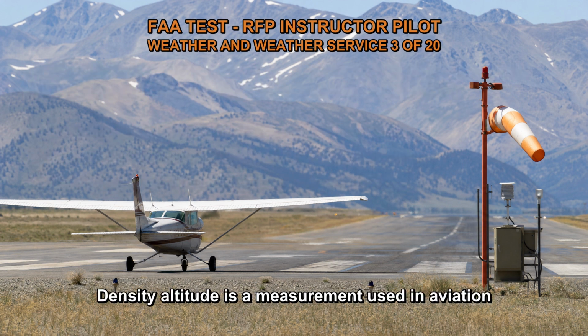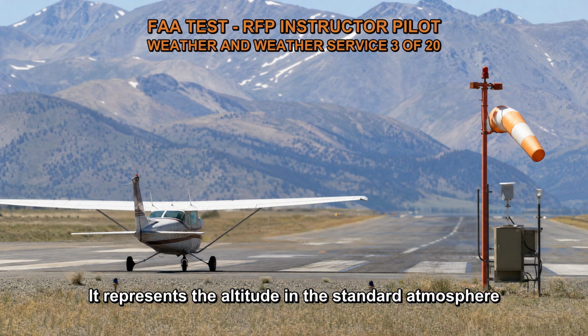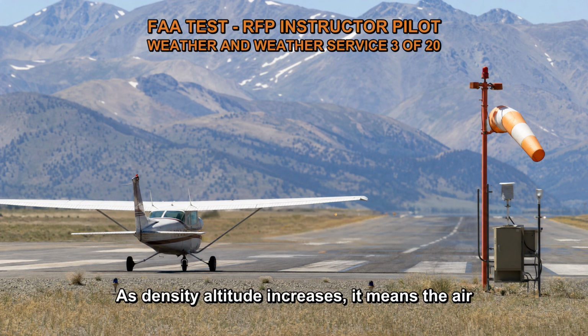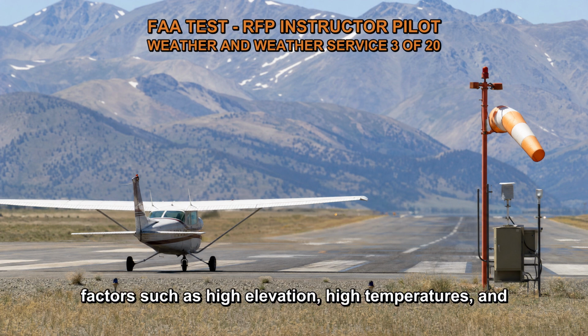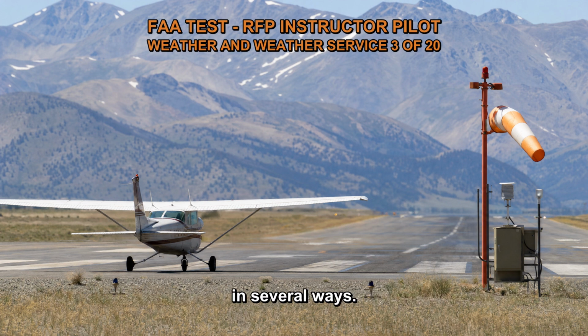Density altitude is a measurement used in aviation to account for the effects of altitude and temperature on air density. It represents the altitude in the standard atmosphere where the air density is the same as the observed air density. As density altitude increases, it means the air density decreases. This can occur due to a combination of factors such as high elevation, high temperatures, and high humidity. When air density decreases, aircraft performance is affected in several ways.